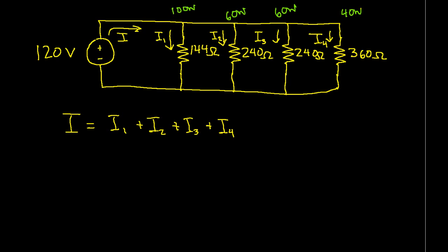Now, at this point, I'd like to take a bit of a digression, because I've discovered that this particular point can be rather confusing, and it's one of the big misconceptions that students have. Sometimes students will think that the node would be wherever I join wires, and my previous picture to introduce KCL might reinforce that misconception. But a node is anywhere I can get to by following a wire.